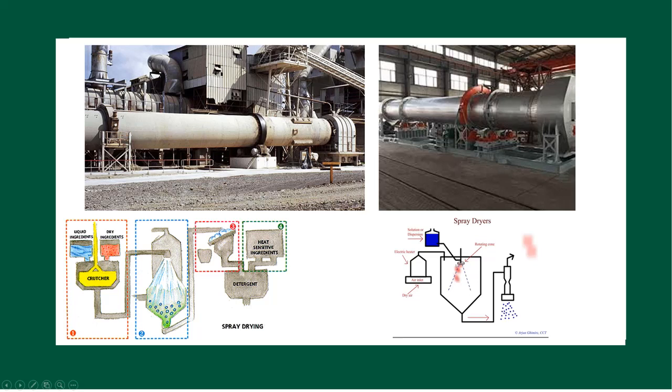This is a spray dryer where the liquid is sprayed using nozzles. So they are micro droplets sprayed in a cylindrical chamber, where you send in hot air or something to take away the moisture present in it. The vaporized moisture will be removed, so the dry solid materials will be collected at the bottom. There are cases where there will be complete removal of moisture, like the milk powder case. On the right hand side you can see the final product is totally milk powder without any moisture present in it. So spray dryers are also widely used in chemical industries.